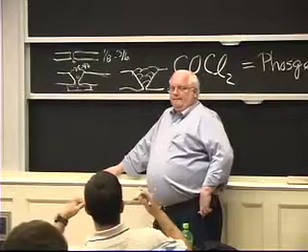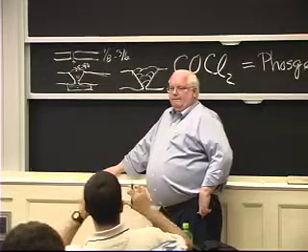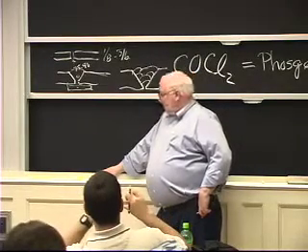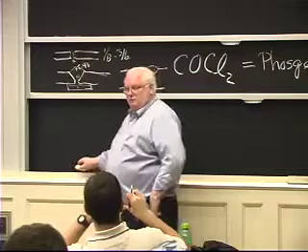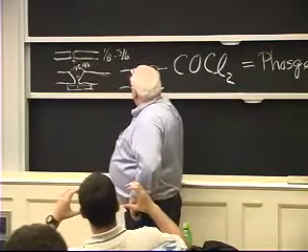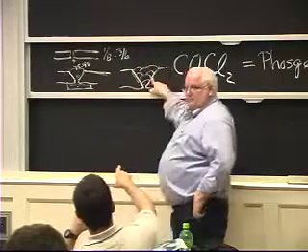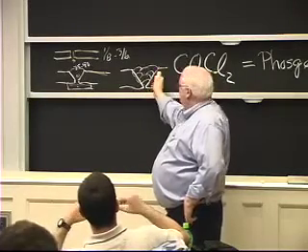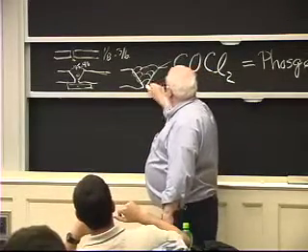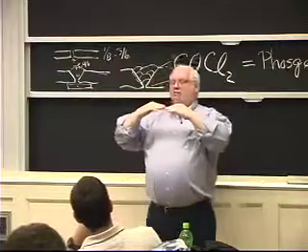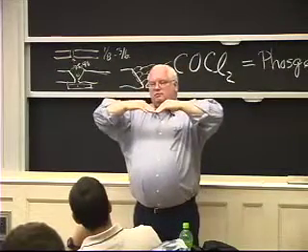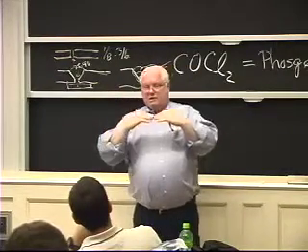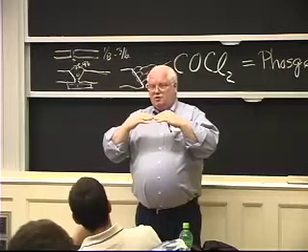So to get the pieces to merge together, aren't you going to end up with a narrower area than 1 inch? Narrower heat effective zone? Well, no, if you've got 2 bars, you have them separated. Is there something in the middle there? Because if there isn't, as you're just melting the 2 pieces of steel together, you know, no. They will distort at an angle, and if you start out flat, they will end up V-shaped. Because it shrinks more at the top than it does at the bottom. And that's a problem of distortion.